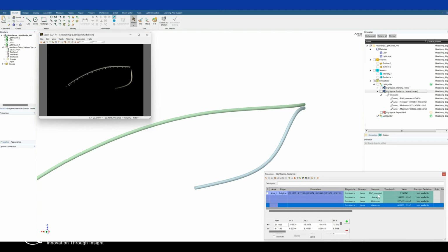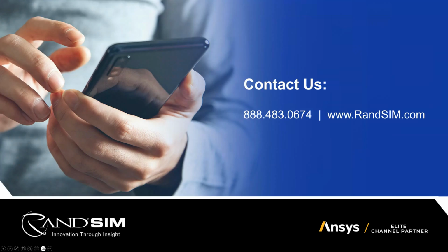Now, all of these parameters, and especially the light guide parameters that we define, like the prisms and all of that, are able to be optimized. So this would be the setup right before you're about to do the optimization. And then when you're ready for it, you can throw all these parameters into a system like OptiSlang and do a sensitivity analysis. You can do tolerance analysis, and you can also just do a regular optimization. So that is that. Lori, I'll hand it back to you.